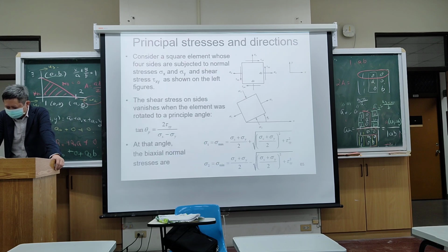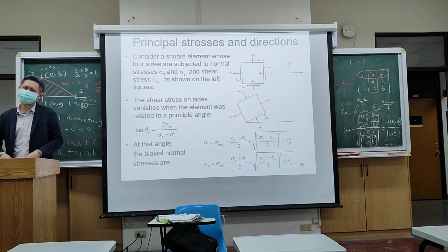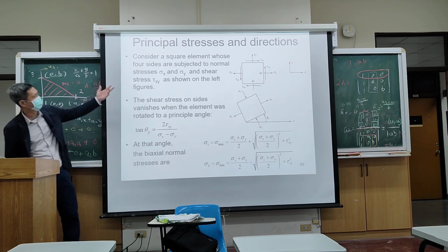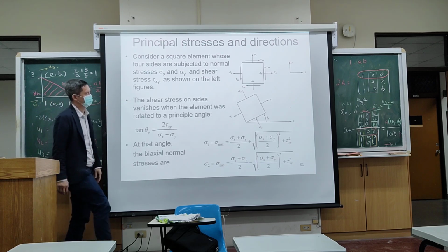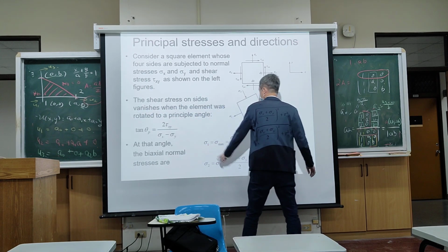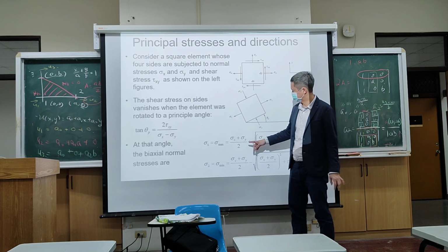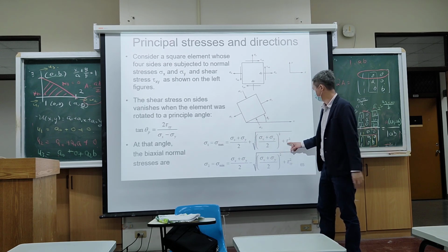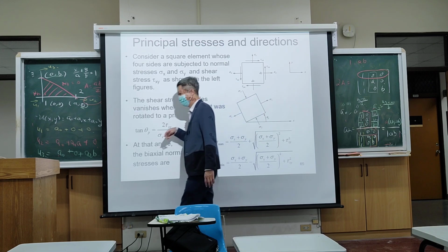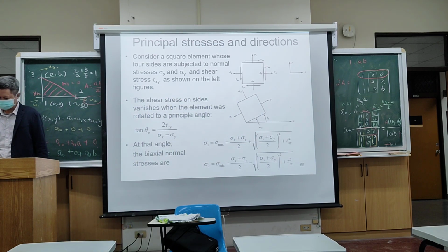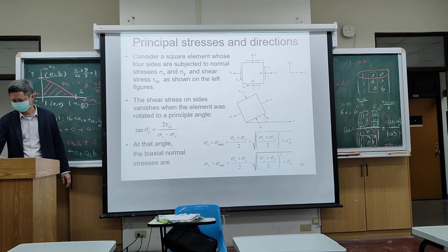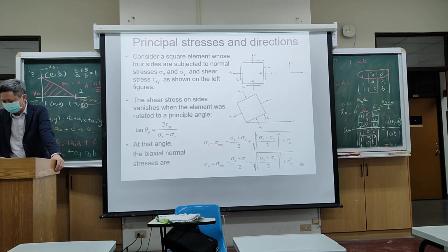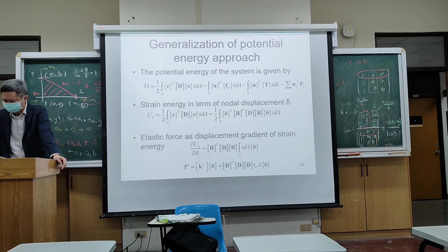the stress-displacement relation. And of course, after you have the stress in the x component and the stress in the y direction, you can apply your principal stress method. Then you can find the principal stress to be the sum of the stress in the x and y directions divided by 2 plus the square root of this sum squared plus the shear stress. So with Mohr's circle you can find the principal stresses, the first and second principal stress, and the principal angle can also be found through Mohr's circle. Okay, so this is a part that if you want you can revise it.